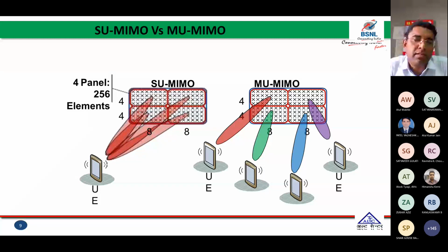On the uplink side, there is a maximum of 4x4, but on the downlink side, 8x8 single user MIMO is the maximum feasible, because it is very difficult to achieve orthogonality between the different propagation channels. So if your propagation channels are not orthogonal and are highly correlated, that means your data throughput will be less.